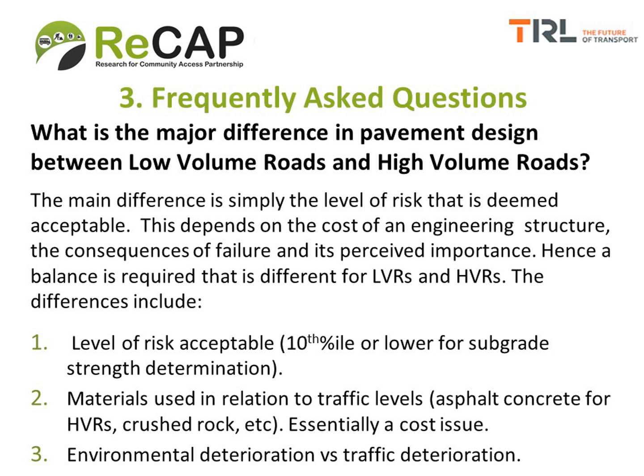But in practice, most of the manuals recommend that for designing for the subgrade, for example, we use a 10th percentile, as I said for the previous question. The risk is higher for low volume roads, but we're still recommending that for the subgrade determination, you use a 10th percentile. The second point there is that for high volume roads, we're looking at the differences.